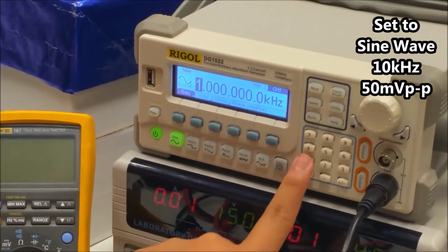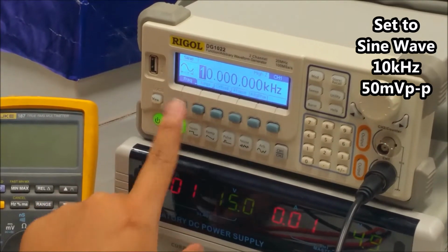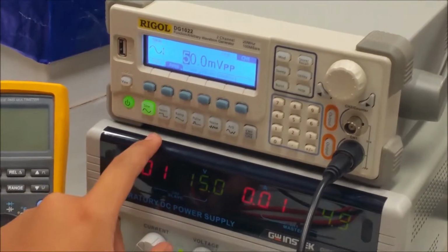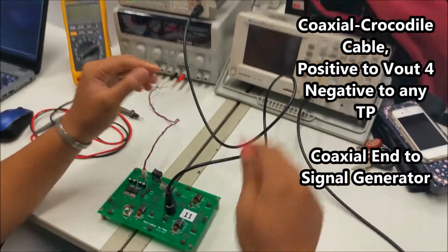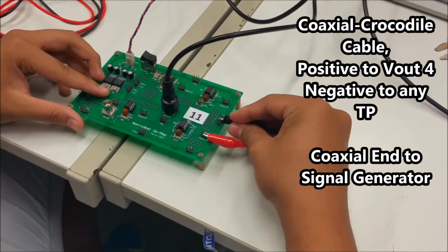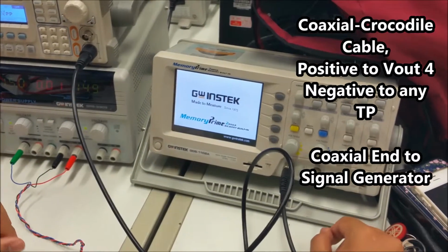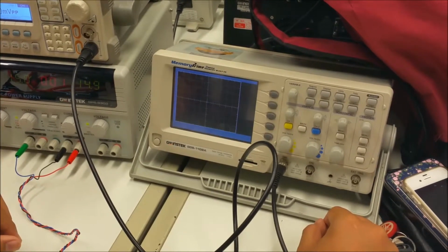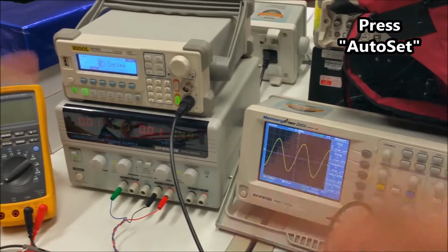Now set the frequency to 10 kHz and voltage to 50 millivolts peak to peak. Now take the coaxial crocodile cable, connect the positive end to Vout4 and the negative end to any TP surrounding, and connect the other coaxial end to the signal generator. Now turn on the signal generator and press auto set and your waveform will appear.